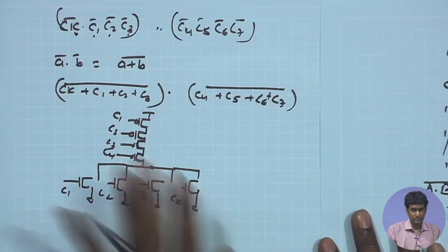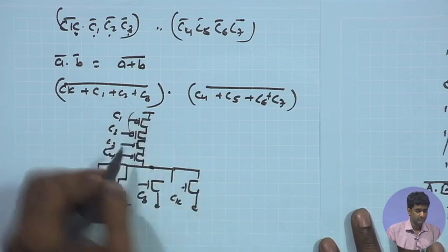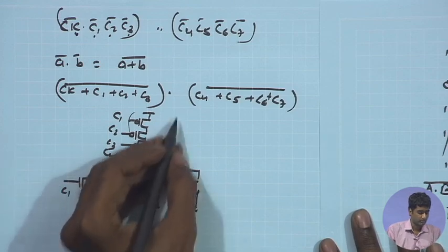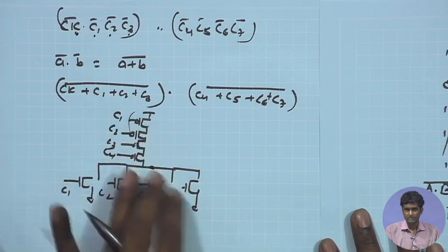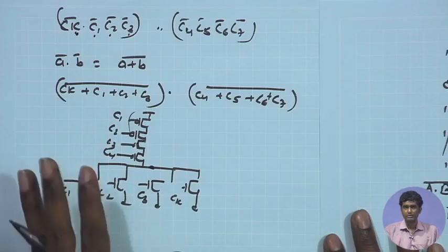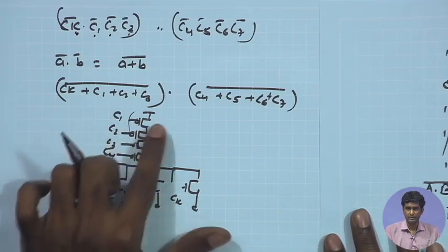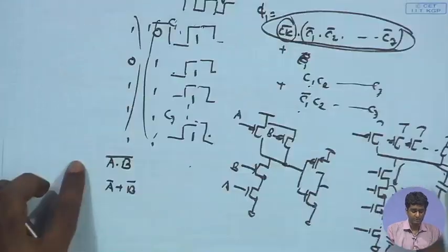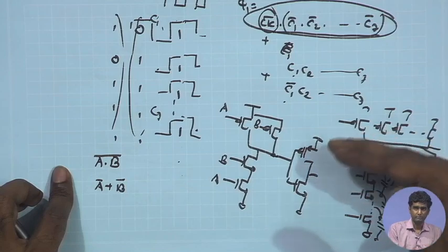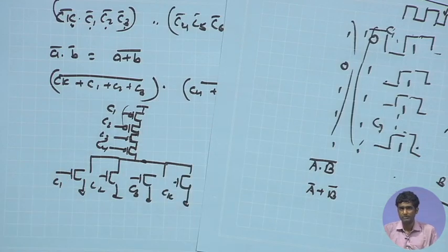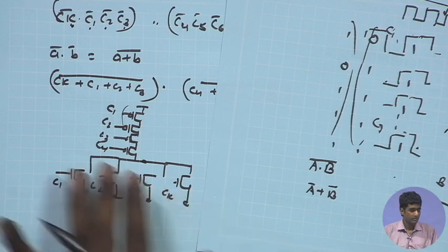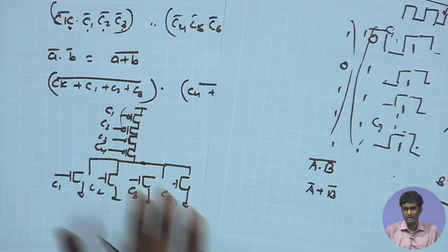And one important point to be noted is that, in general, the mobility of the PMOS in 180 nanometer can be half the mobility of NMOS, and as a result, the speed of the PMOS transistor can be half the speed of the NMOS transistor for the same dimension. So, if you stack PMOS transistors, it leads to slower speed than if you stack NMOS transistors. The speed of 4 stacked NMOS transistors can be significantly better than 4 stacked PMOS transistors, because the mobility of the PMOS is 2 times lower in 180 nanometer. That difference has vanished for lower technologies. For lower technology nodes, that difference is very minimal, but for older technologies like 180 nanometer you will still get at least a 2 to 2.5 ratio.